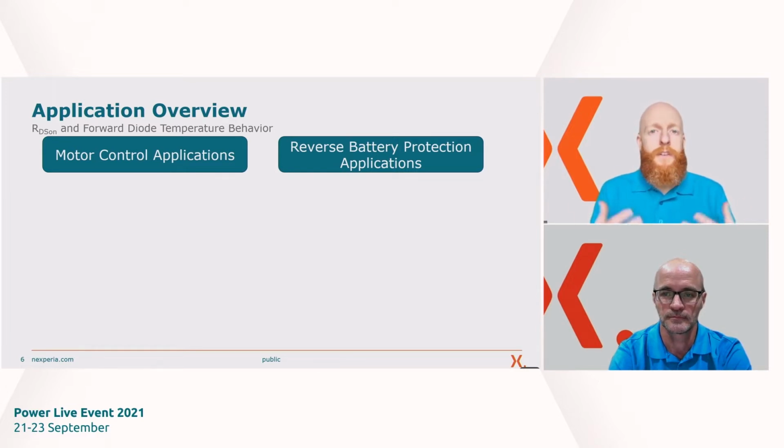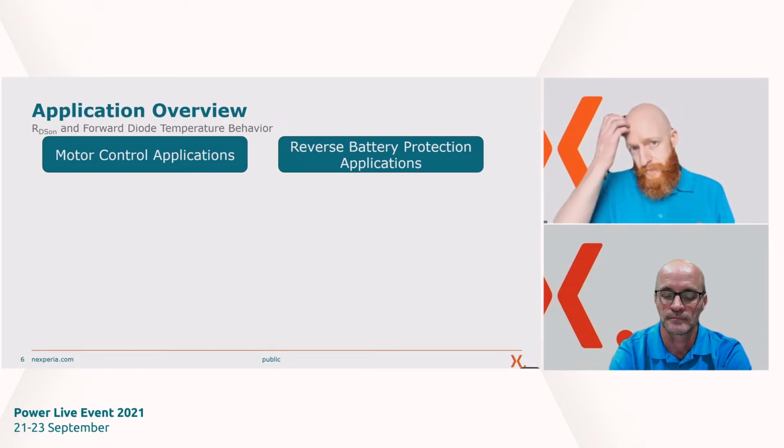And quite often, and for a MOSFET specifically, one of those limits is the junction temperature. And for our power MOSFETs, that junction temperature limit is 175 degrees C. So whenever you're doing a design, you need to make sure that whatever powers you are dissipating in your system, you can predict, you can measure and model and ensure that you're staying within those temperature limits.